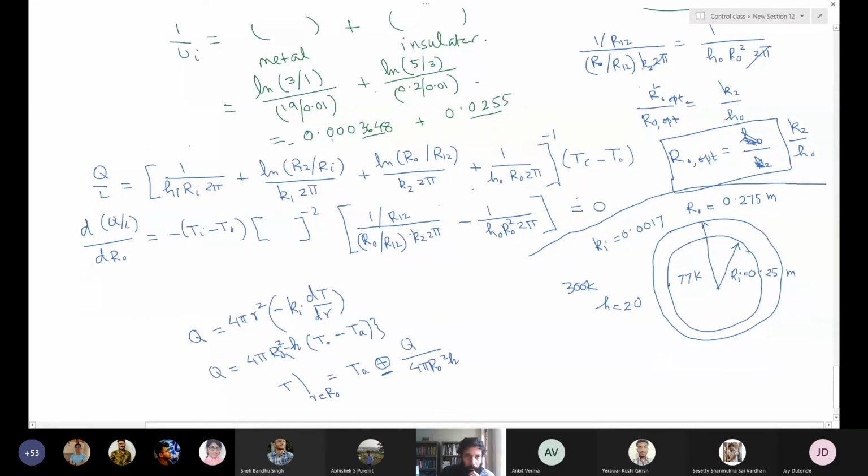So in Newton's law of cooling, we write this away heat flux as H times (T surface minus T infinity). So this is the direction away from the surface. Here it's written as H, T surface as To, and TA. So this is away from the surface, the positive r direction flux. And this is also a positive r direction flux. Should be fine.